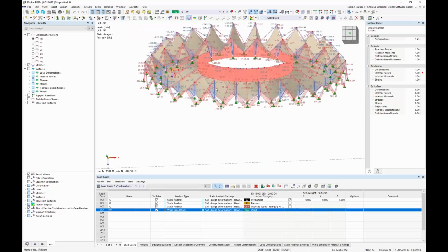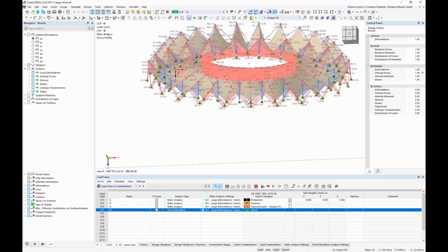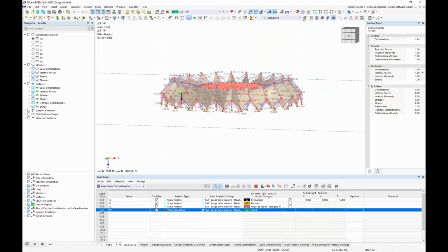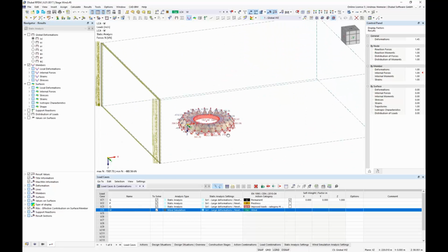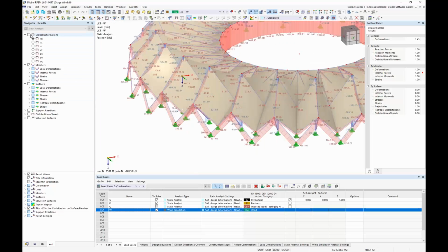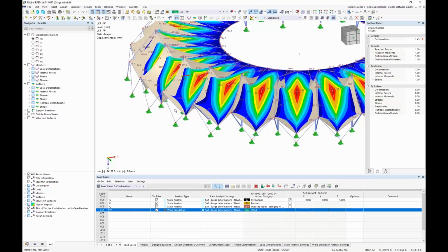Here we have, for example, the internal forces, normal axis forces. Maybe only I rotated that we have now, yeah, exactly. And even we get deflections on the structure. All this feedback of the structure is now given according to these loads, and now with this information and this real load distribution of wind load, you can go ahead like I just showed you before.